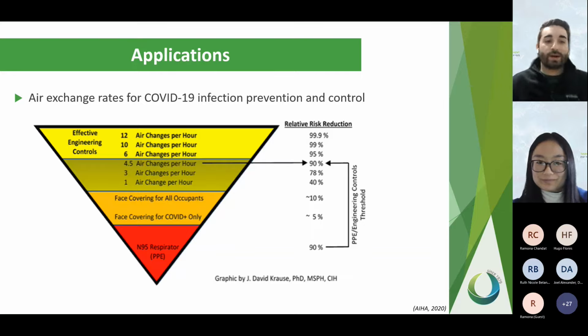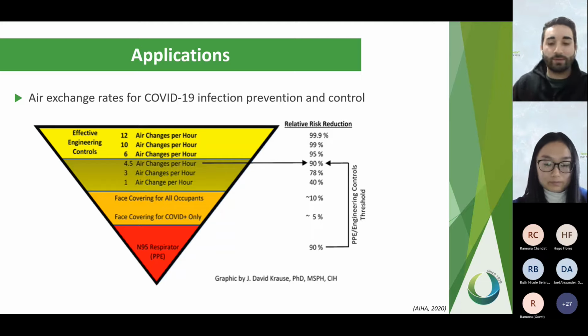I'd say the first thing that you would want to do before people return to work would be to conduct a ventilation assessment to make sure that, one, your system is working properly, but at the same time that you're providing sufficient protection against COVID, the SARS-CoV-2 virus, but then you also have your indoor air pollutants itself. Since the space wasn't occupied and maybe the ventilation system wasn't operating as it usually would, you have the potential for indoor air contaminants to accumulate in the space. So that'd be the first one.